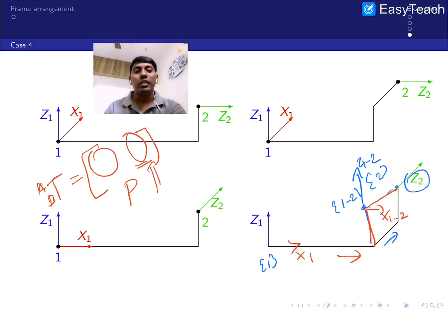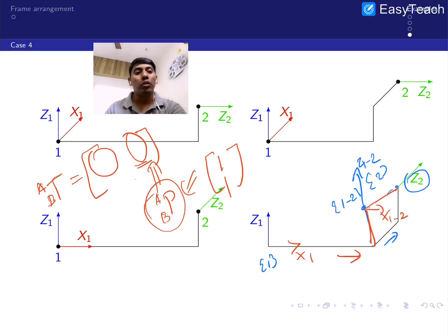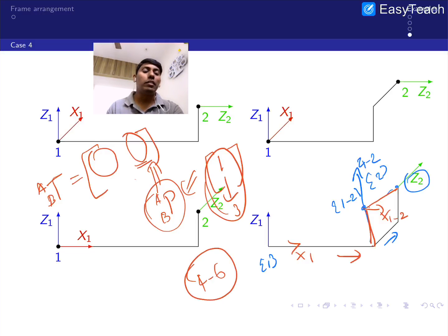In the sense, you can see that whatever you choose for your position, the first 3 axes are predominantly defining it. So these 3 are what you call the major axes, which are 1, 2, 3 of your joint axes. Then the next 3 axes, 4 to 6, predominantly play the orientation role, so they are called minor axes. Why are they called major and minor?